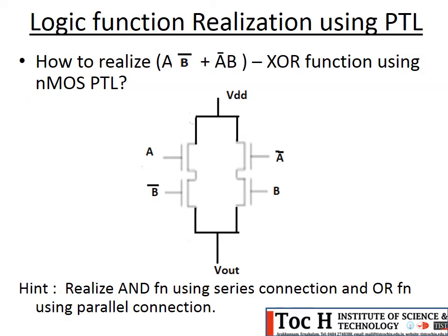Let's see how to realize an XOR function. What is an XOR function actually? A B complement plus A complement B. You need not bother about anything else, you only focus on these logic functions. What you can see is A into B complement, so A into B. Here is an AND function.